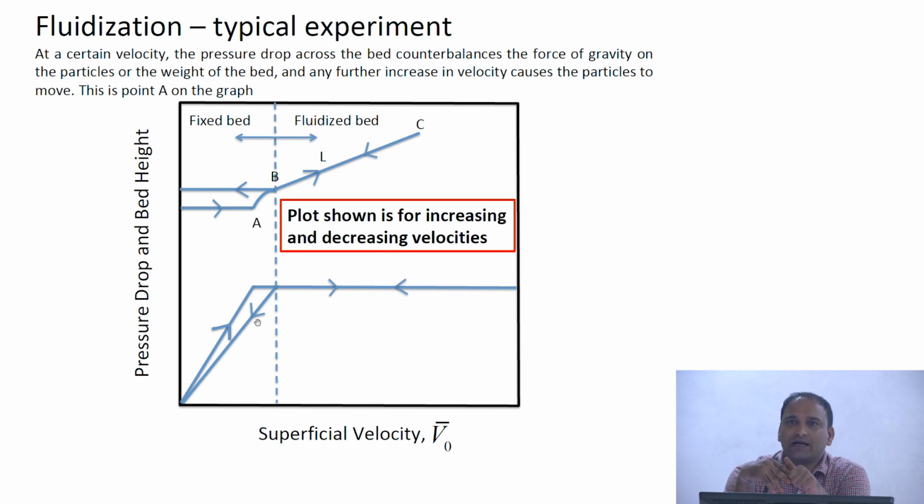And it is known that I can create a packed bed of different porosity starting with the same column and particle combination. That means if I take a vertical column and pour solids, they pack in a particular way and give rise to a bed of particular epsilon. Now if I do exactly the same process, but in the end I shake it up, they pack a little differently. So that initial line depends on the kind of operation that you do in order to create the packed bed.